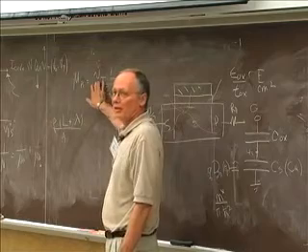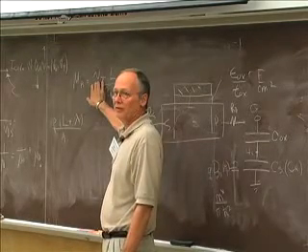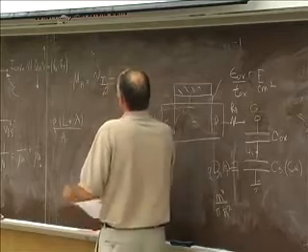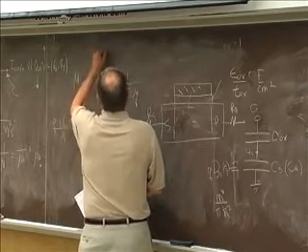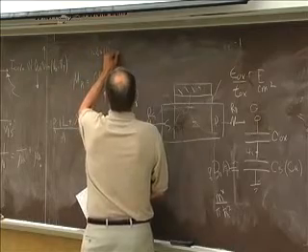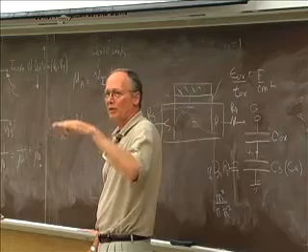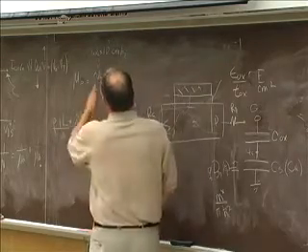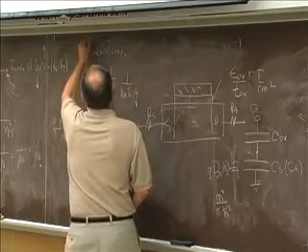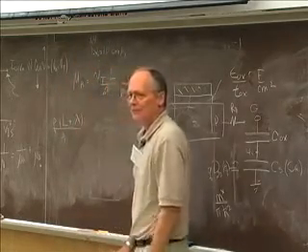one of the things I really should have said, this really depends on where the Fermi level is in the band. When you're a non-degenerate semiconductor, it's independent of the gate bias, and it's 1.2 times 10 to the 7th centimeters per second. When you start pushing the Fermi level up in the band, that velocity gets higher. So under typical on-current conditions, I think this is more like 1.4, 1.5, something like that.